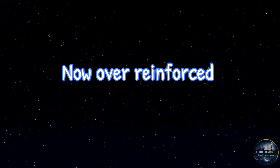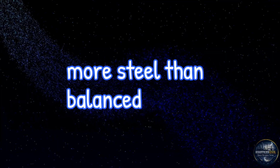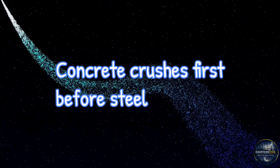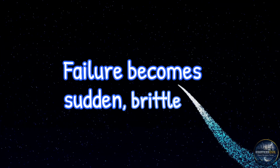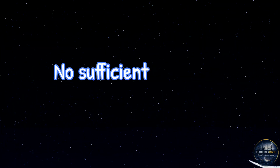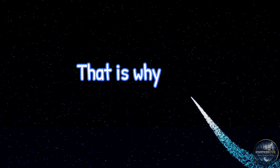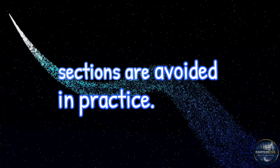Now over reinforced section. Over reinforced section contains more steel than balanced section. Concrete crushes first before steel yields. Failure becomes sudden, brittle, and dangerous. No sufficient warning is available before collapse. That is why over-reinforced sections are avoided in practice.